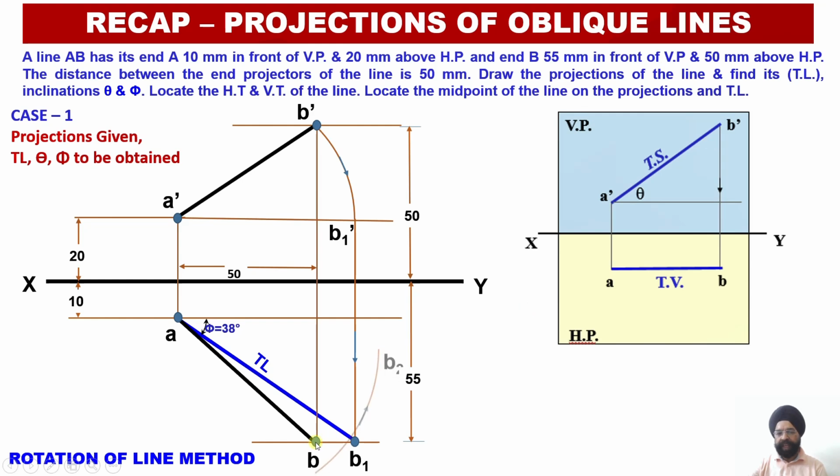So now again you see I am going to have my needle point over here. This will be my locus line. Now up to this locus line I need to draw this arc. So keep your compass needle over here, open compass this much, draw an arc. And since this is the second rotation, I will mark this rotation as the second one. So it will be B2.